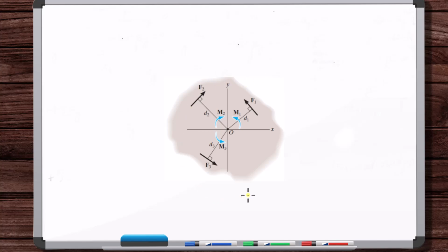Okay, so here's another illustration of that perpendicular moment arm distance, right? That's how you can view it in 2D if you want, or you can just break these down into components and sum the moments of 6 different components of these 3 vectors in total, or you can just find the perpendicular moment arm distance and do F1 times D1 plus F2 times D2 plus F3 times D3.